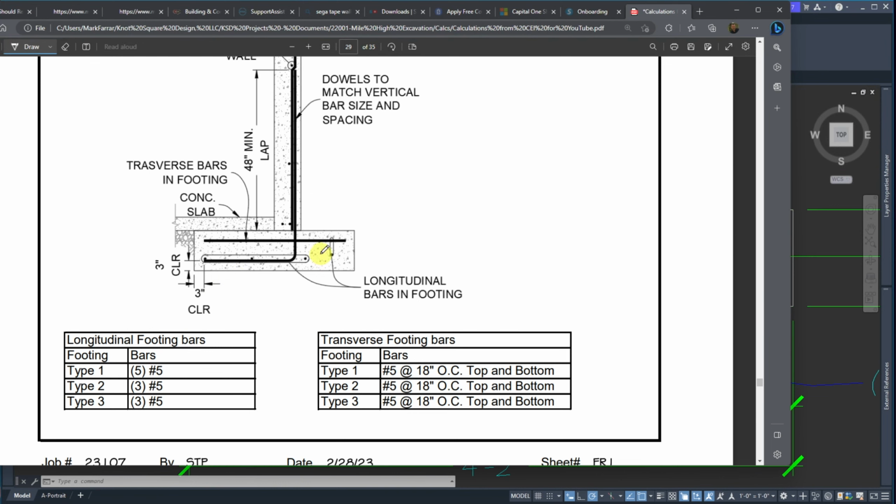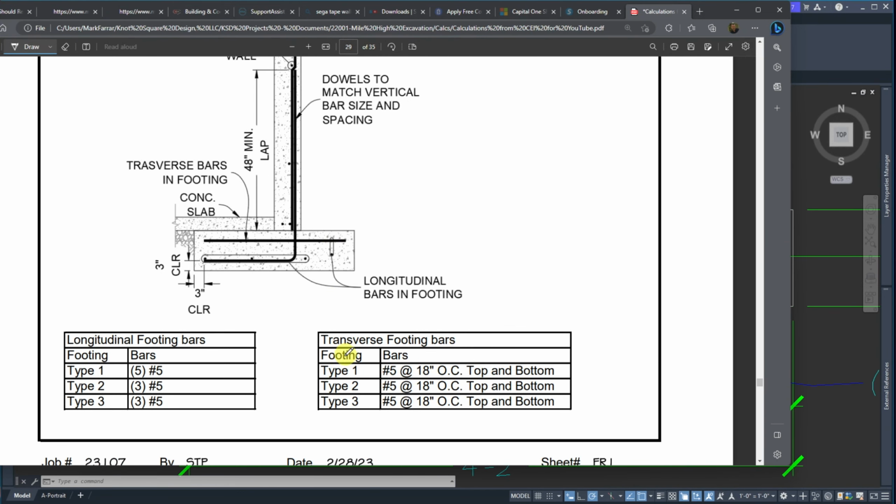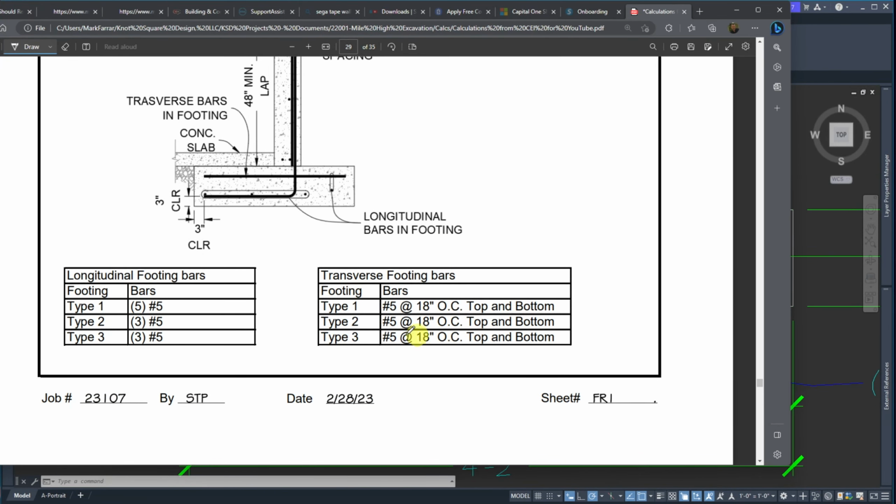So I need to see if we are counting a bond beam, if he wants one up here with this guy, where exactly he would like that 5th bar. Since it's not shown here, it may be up in the literature. If I find that later, I'll point that out. But the type 1 also, and the type 1, just so you know, type 1 is the definition for this one that we showed way up top. That's 8 feet tall. And then we have one that gets shorter, and then one that's shorter still, and that's why we're getting into these lower numbers.